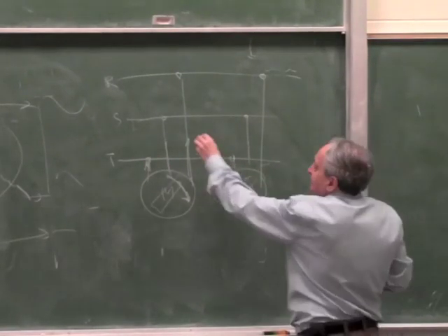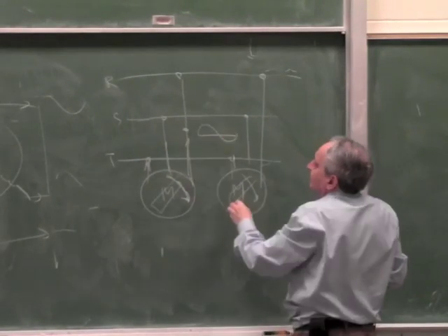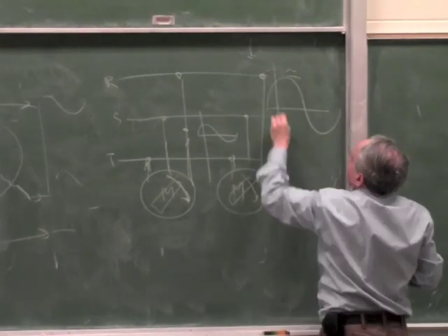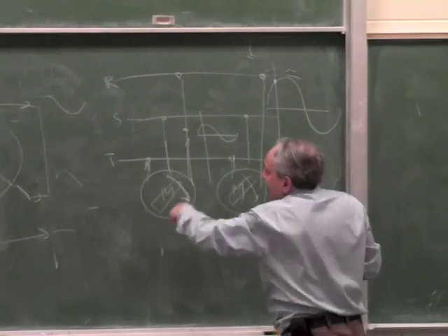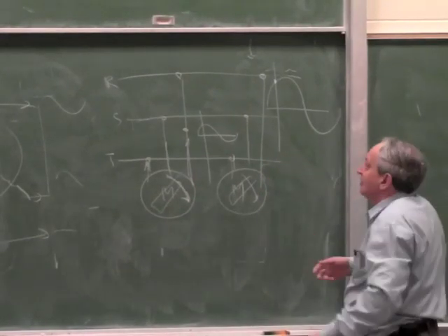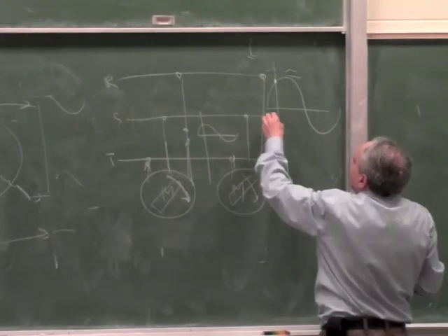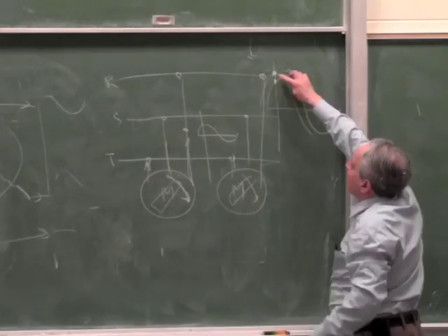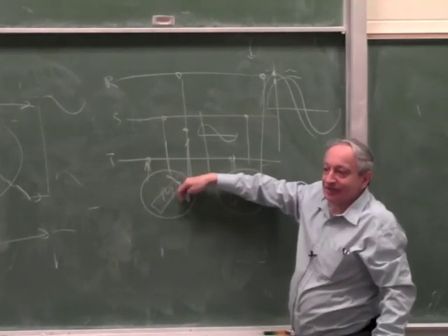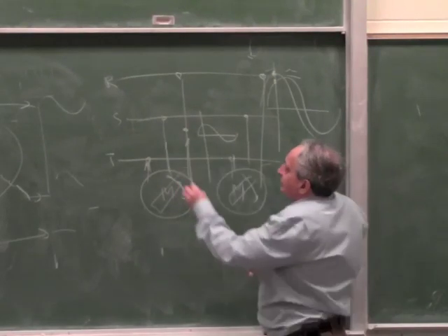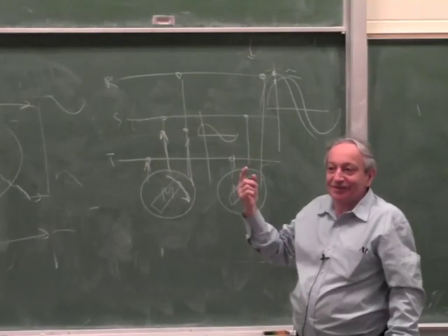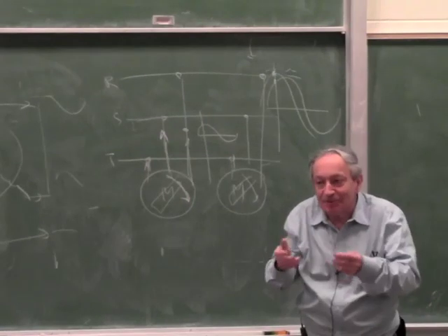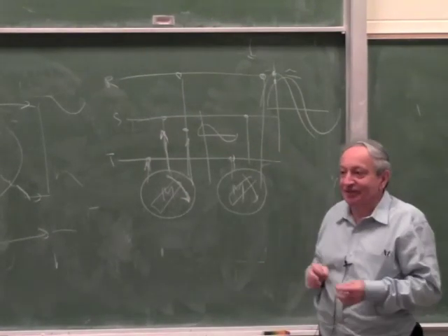Let's say that at this point, the phase is a sine wave like this, and this is a point in time. I'll draw it here larger. Let's say this is the input phase, and we are at this point in time. Now let's say you're turning the motor faster than it wants to turn, so it generates its own phase, which is a bit ahead, like this. So its voltage is going to be higher than the voltage of the phase connected to it. Instead of the current flowing into the motor, current will actually flow back. So when you have many motors connected to a grid, if you want to speed up the motor, you're actually feeding power back to the grid.